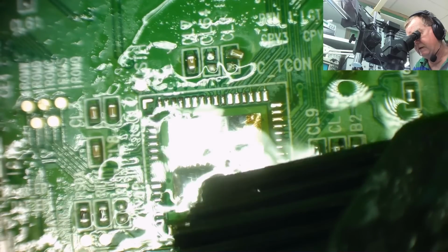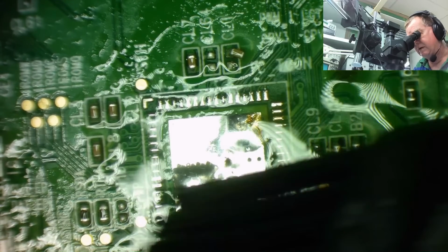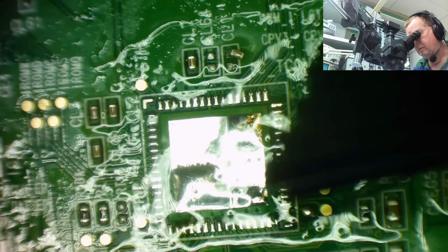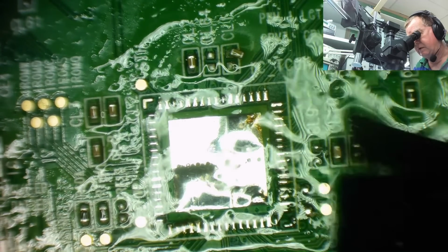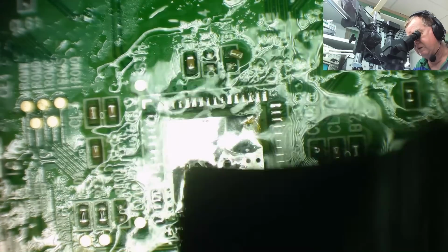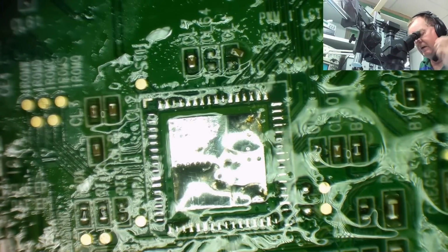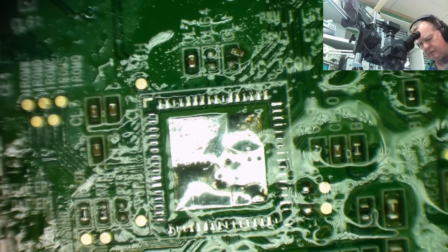We probably have to remove this bit, and the knack of this is to get this flat, certainly so it's not raised above these legs, otherwise it won't solder. I think we took a capacitor off there. We can replace these off the other board, it's not an issue. The main thing is going to be getting this chip replaced. Yeah, I still have to take some solder off that centre.